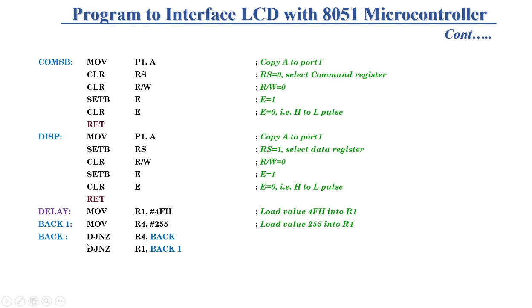That means this subroutine will be executed 4FH into 255 times. RET. So after execution of this instruction, it will return to the main program. So in this way, we can write the data to the LCD.